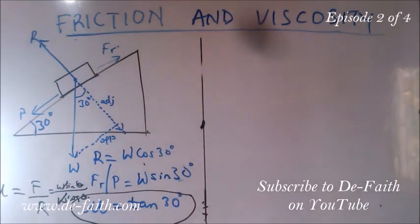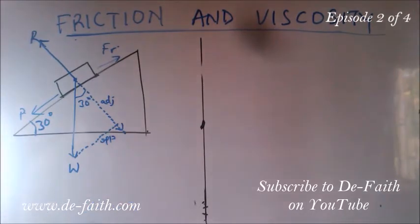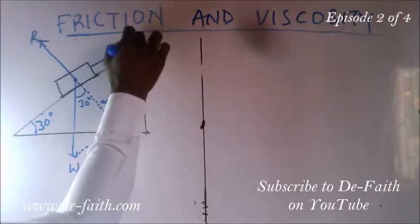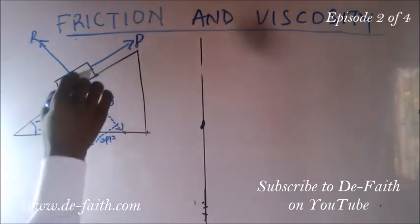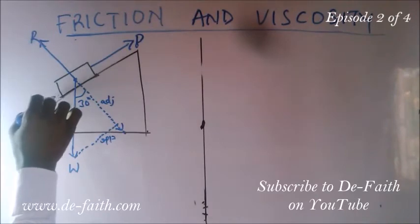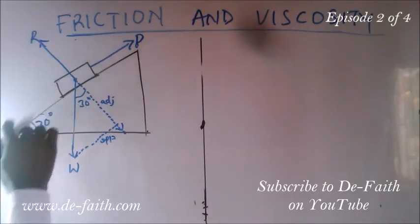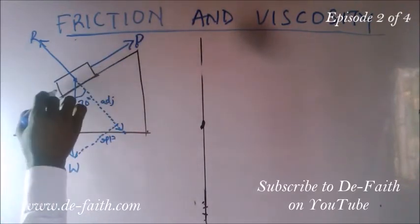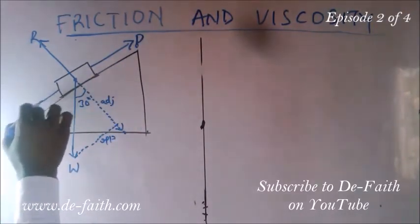So back to our question. We're told that this body of mass 4 kg is on the point of slipping down a plane which is inclined at 30 degrees to the horizontal. So what force parallel to the plane will just move it up? That means we are looking for a force which we call P, that is a pull, that will move it up. That means as we are pulling it up, there will be a form of friction that will want to prevent this body from being pulled up due to the surface. So we have a frictional force.